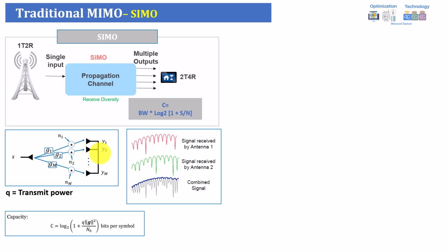This means that the UE, or the receiver in general, will combine the observations from all these antennas, which is four antennas, and instead of using only one of them, the strongest one, it will take all the observations into consideration and combine them into one, and detection is done on this combined observation, which will give you a much better signal.